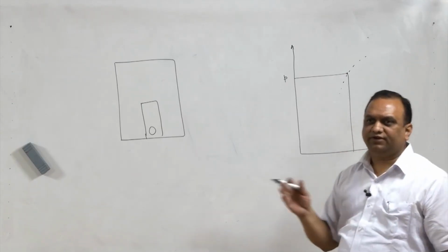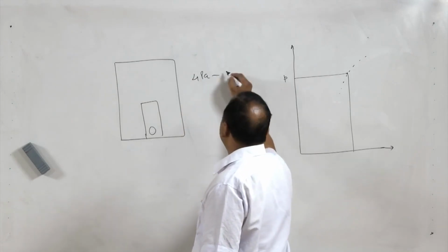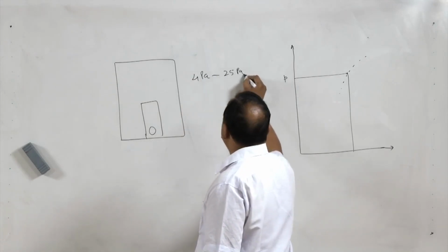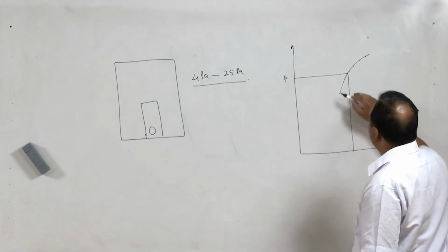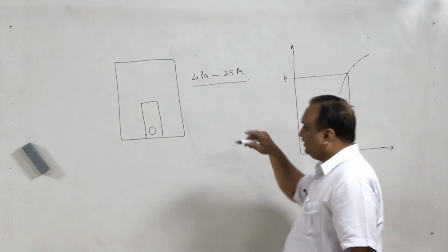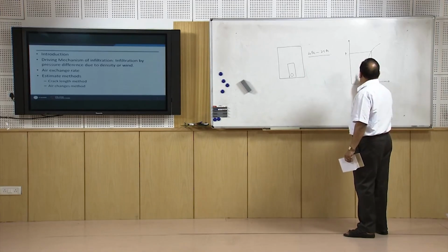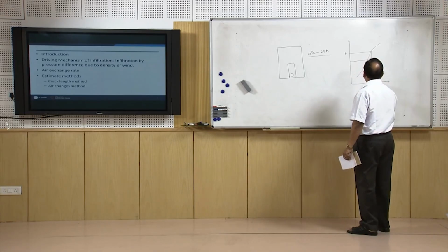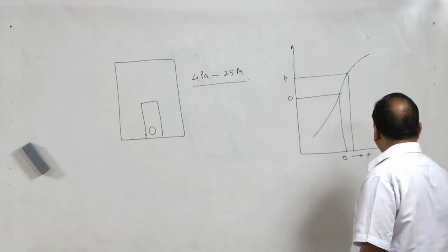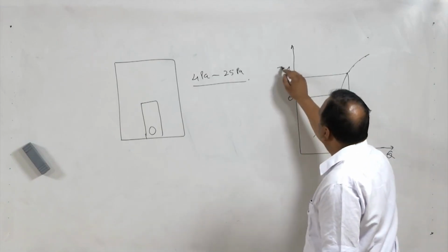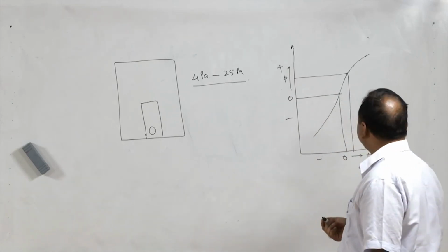The variation of pressure is between 4 Pascal to, let us say, 25 or 30 Pascal, and we get a curve like this. Similarly, we start creating vacuum in the building also, and we get another curve. Here, let us say this is 0 pressure and 0 flow, this is positive pressure with positive flow Q, and this is negative pressure, which is suction from the building.